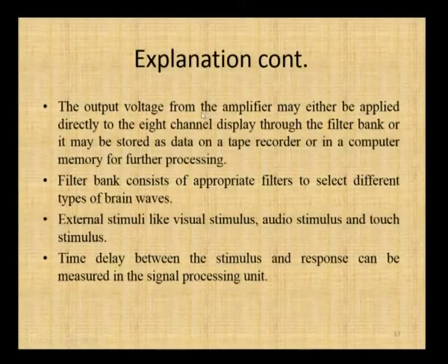When you consider the output voltage of the amplifier, it will be applied directly to the 8 channel display through a filter bank, or it will be stored in the tape recorder for future purposes, or it can also be stored in the computer memory. The filter bank will have appropriate filters for selecting different types of brain waves.